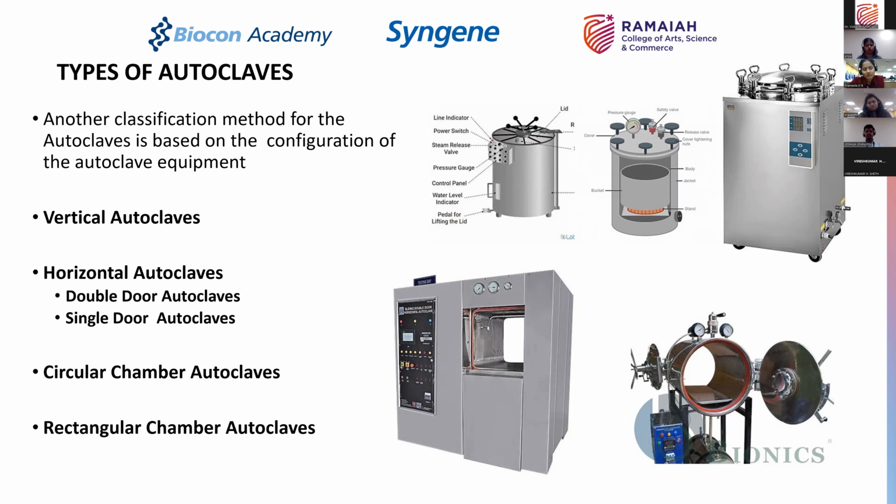So how do you take a decision on this? Generally, when you are talking about sterile manufacturing operations, you want to unload the sterilized products into a cleaner area. So you would load it from one side and unload it from the other side. The loading side is generally of a certain classification depending on the kind of sterile manufacturing you are doing, and the unloading side is a cleaner area.